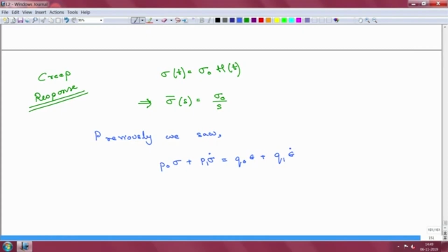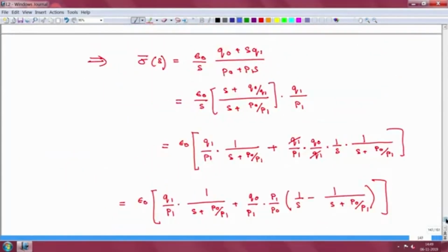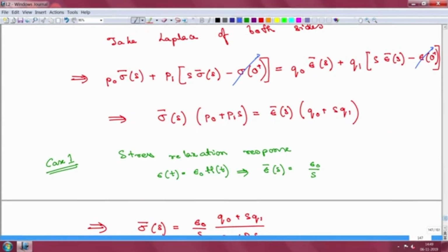There is one more thing I want to point out, that there are 4 coefficients here in the ordinary differential equation, but your original model only has 3 constants E1, E and eta. So, the 4 coefficients here are not independent. There are actually in reality only 3 coefficients and the 4th one is a dependent one. Okay. So, now this part is something that we can still reuse, right.